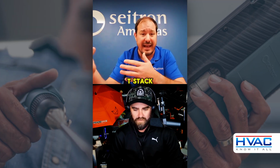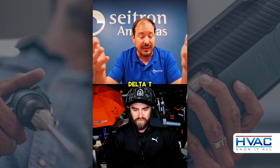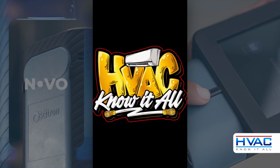And every analyzer takes your T flue or T stack, your stack temp. And then you'll see in the reading on there says T air. And then you have delta T. And what the analyzer does is it knows your fuel, calculates CO2, takes your delta T, and that's how we get efficiency.